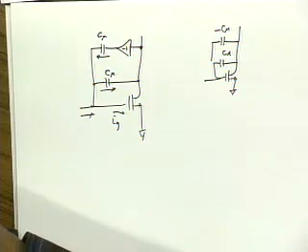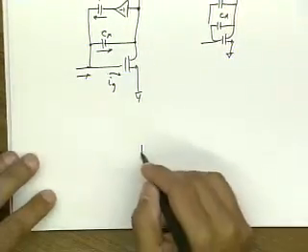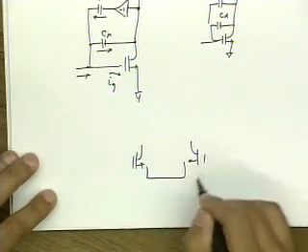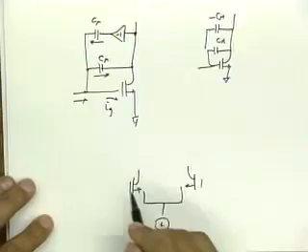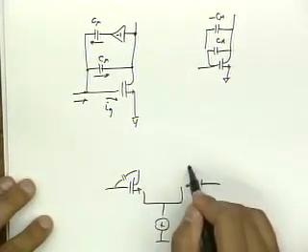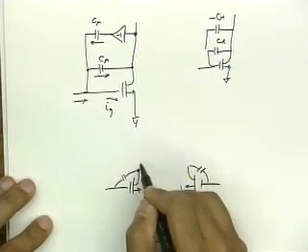That makes sense, right? Well, in integrated circuits, there's a really easy way to do this. You just cross-couple your devices. So if I have a differential pair, for instance, then automatically I have the output voltage and its inverse available to me.